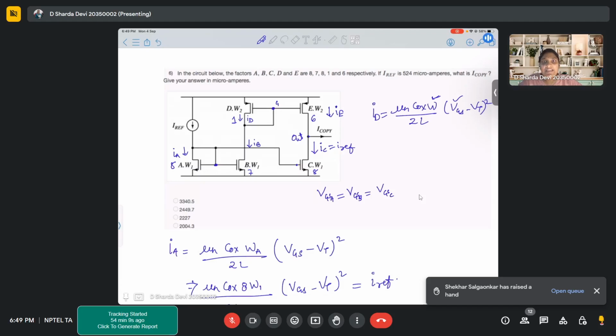But there we cannot directly say it that way. Yes, we can say it, but it's just that one is an NMOS, another is a PMOS. So I denoted it in terms of both, but it's better to write your current ID in terms of PMOS, because your IE will also come in terms of PMOS. So it will be easy to relate, because of mu n Cox W by L, or mu n Cox by 2 and mu p Cox by 2.